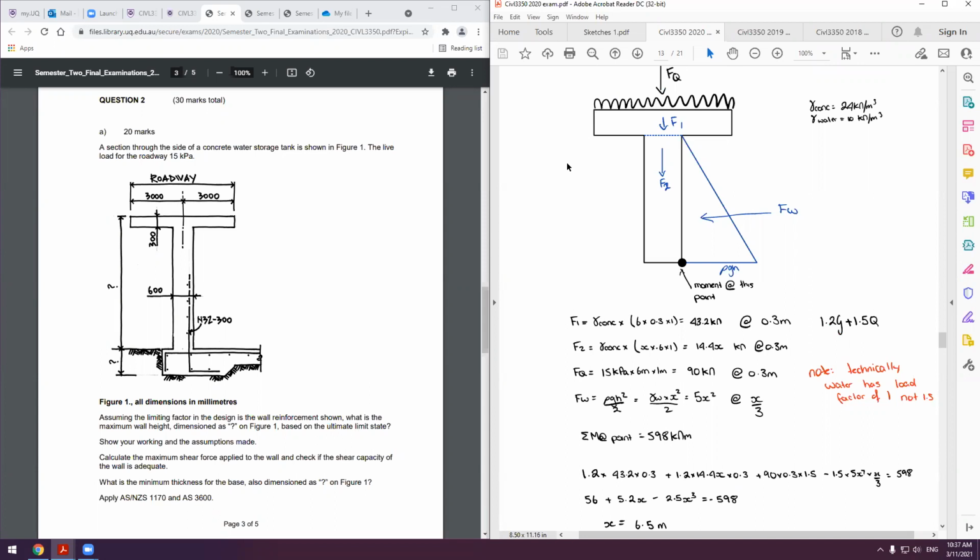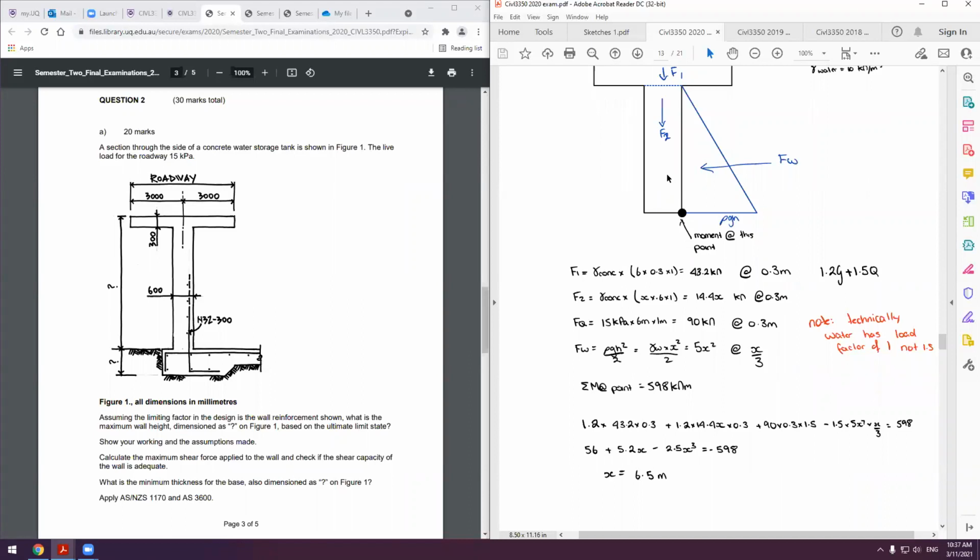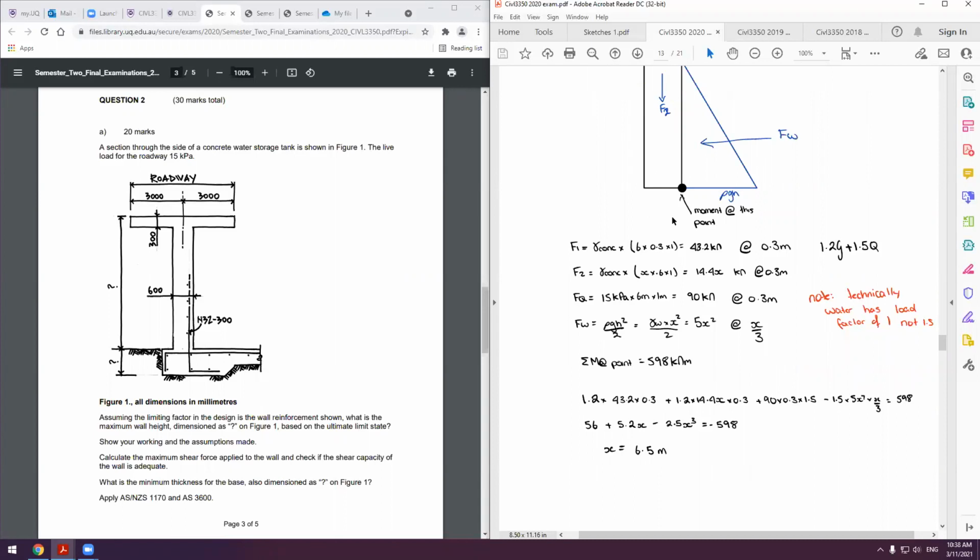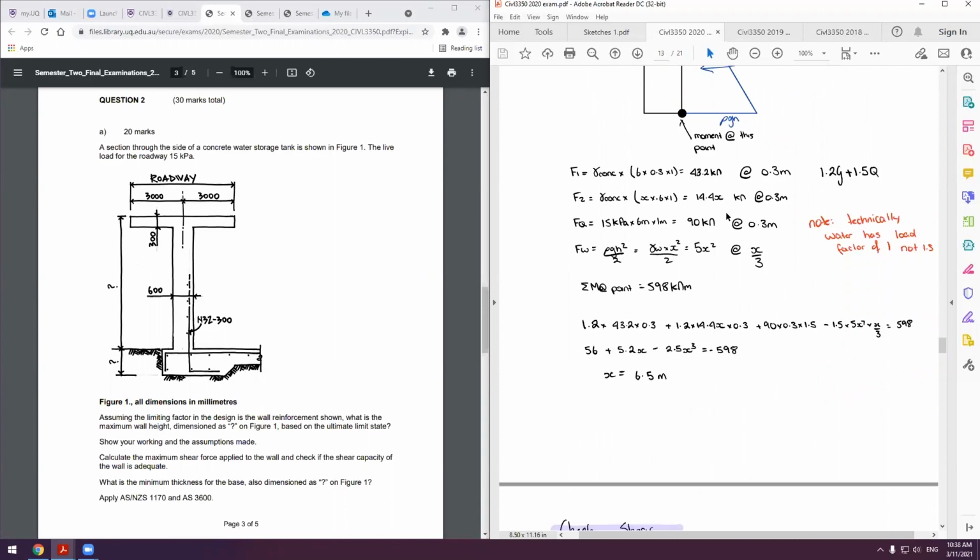Would it be insane to, because it's a live load, it could go on like half the slab, so you could take the worst case live load? Yes, so that is true. When it comes to road designs, it changes. So in this subject, in this exam, I wouldn't bother. I would just assume it over the entire length and do everything per meter width. But technically, when you're dealing with roadway design, you have like 3 different locations that you have to check across. I wouldn't really bother in this case. You can, it would be critical if you just had it on like this half. Write it, note it down. But you don't really have time to think that in depth.